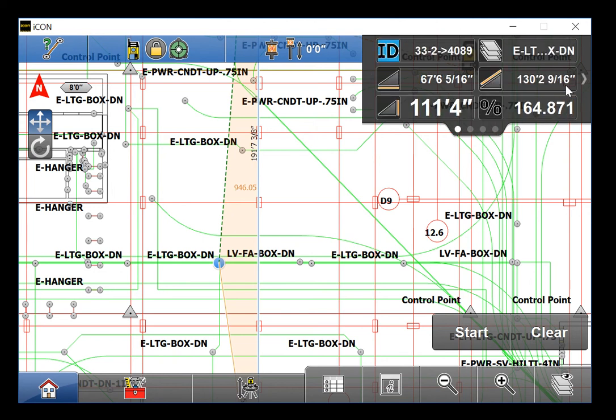Previously, we had no slope data, but because the point has an elevation associated with it, notice that the data changed as it shows us information between that point and the line I have selected. Flipping through the upper right pages shows you the data I previously defined. Notice that we still don't have volume data.